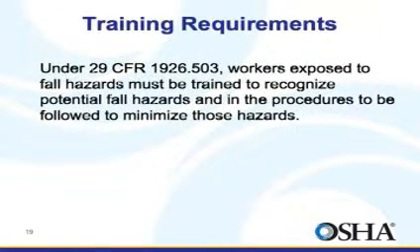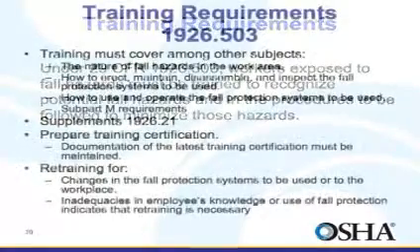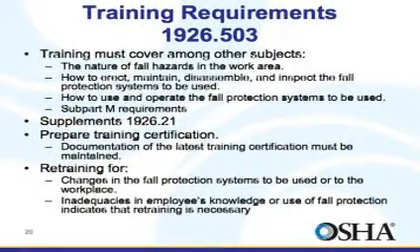Training is an important component of any fall protection program. The workers who actually wear and use the equipment must be thoroughly trained. Employers must train their workers how to recognize and avoid unsafe conditions. Workers must also know the requirements of the standards and the regulations that are applicable to their job. Training plans must also include procedures for conducting retraining to correct less than satisfactory fall protection performance by workers. All training must be documented, and the most current certification must be available on site.